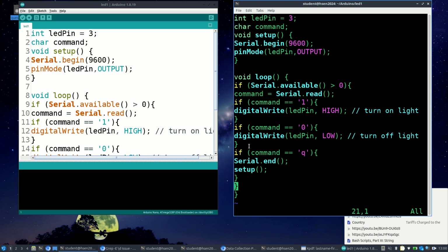Everything is pushed in. Okay, the important stuff, that's that, right? The resistor is only to control the current, so one's going to be brighter than the other one. Some are 220 instead of 270. Oh, are they? Okay, I didn't realize that. Anything that has a third stripe brown would work for you. So 220 is red, red, brown, and then probably gold after that, right? 220 is fine. Remember, we used 220 before. I had just heard that we were out of 220s, and that's why everybody got 270s, but I didn't realize some people got 220s.